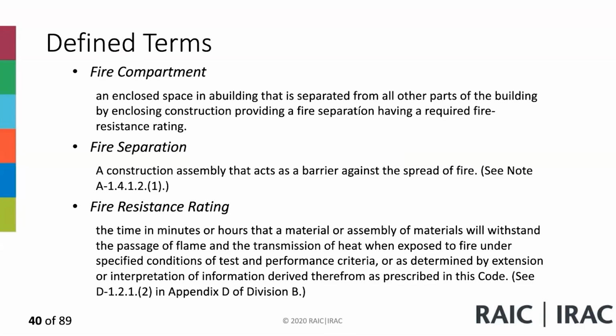Other defined terms, the fire compartment: an enclosed space in a building that's separated from all other parts of the building by fire separations, having a required fire resistance rating. A fire separation is a construction assembly that acts as a barrier against the spread of fire. See the note, so there are notes and clarification related to that.